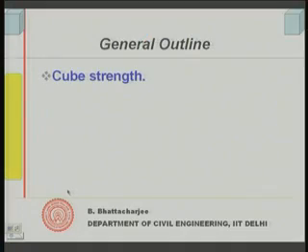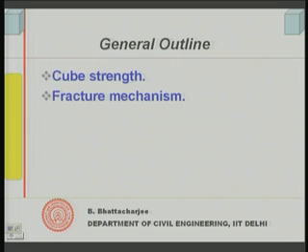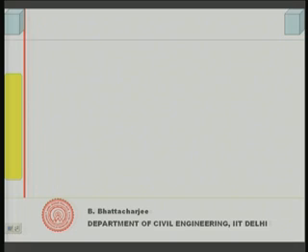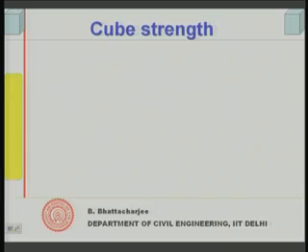First of all, we shall be talking about cube strength, because that is the conventional way we measure the concrete strength. We will follow it by the fracture mechanisms in concrete. We will look into the role of bulk and ITZ porosity, we will define them appropriately, and then the role of water cement ratio. Right. Now, let us see how we measure concrete strength first of all.